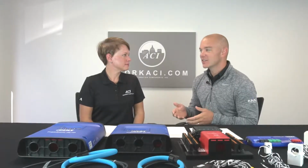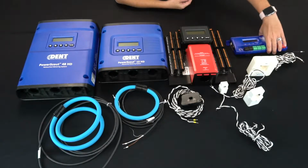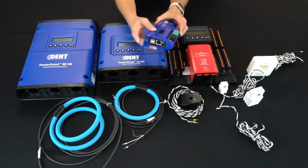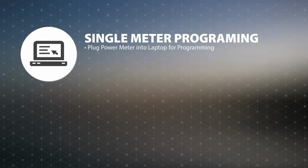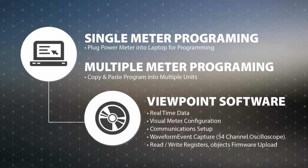How easy is it to configure and install a power meter? That's a great question. It is exceptionally easy. First off, you plug the meter into your laptop via USB cable to do all of the programming with the Viewpoint software. So you can do all the setup in your office before you even have to go out and open up a panel. If you have multiple meters that need programming, it's as simple as copying and pasting that program into each meter right there at your desktop, at your computer.